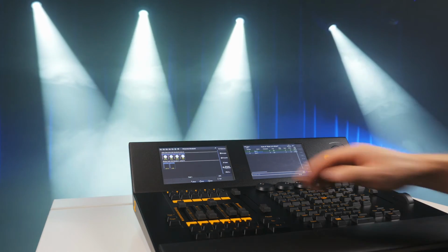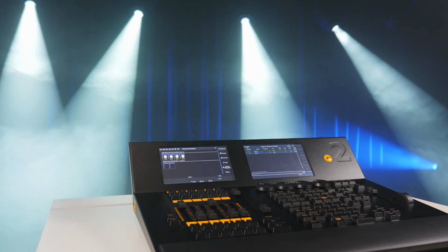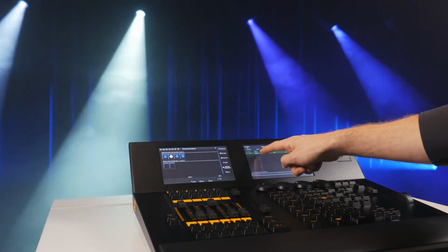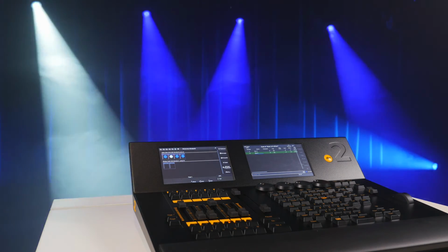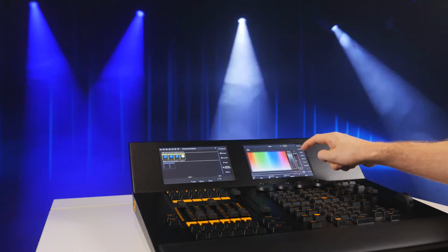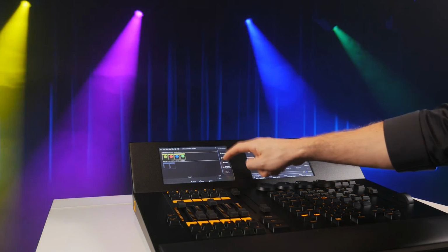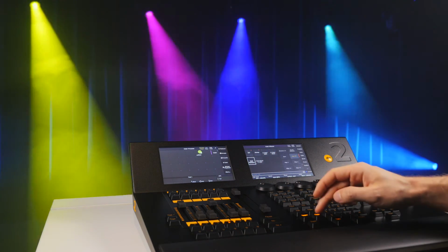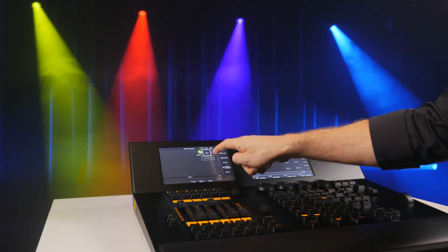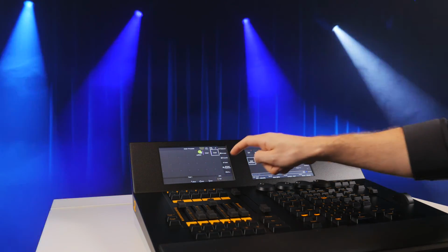Effects can be stored with static values into cues in exactly the same way as we've shown you in previous videos when storing cues. Effects will also obey cue fade times. If we want to use an effect more than once, then we can store it into the same location we stored our presets. We simply set up our effect, bring up the appropriate preset page, then press Store and choose an empty location to store it. We can now quickly recall and use the same effect over and over again.